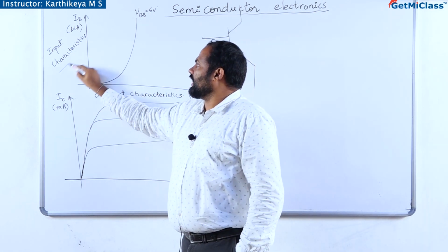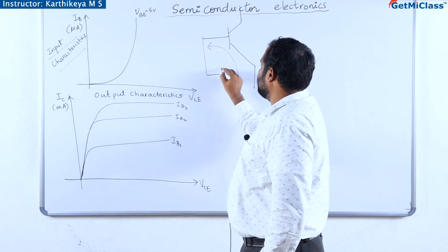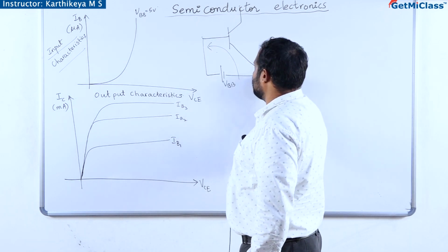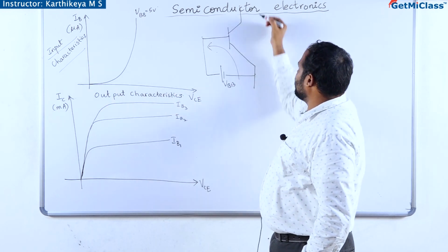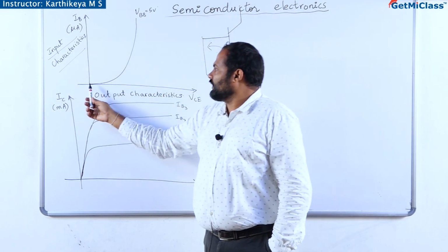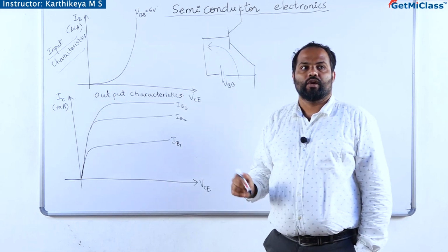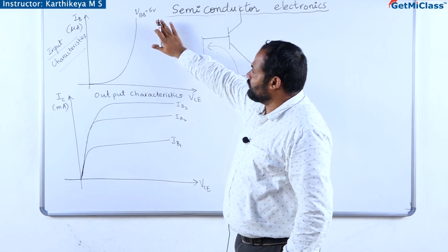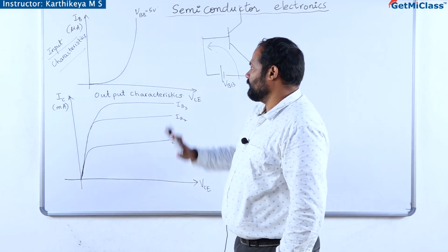So, the input IV characteristics that you get by maintaining a constant potential difference VBB, when the voltage across the collector and emitter changes, give you the typical PN junction forward bias IV characteristics, which will be taken as the input characteristics even for transistors.